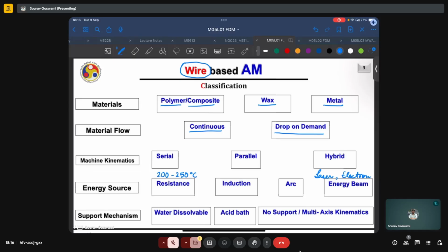Typically, as we have been discussing over the past 6 weeks, we want to have some distinction between our build material and support material. If our 3D printer has the functionality of multi-material printing, we can simply use two different materials, say one of which can be susceptible to chemical attack, or there may be some other way by which one can selectively be removed while the other one stays.